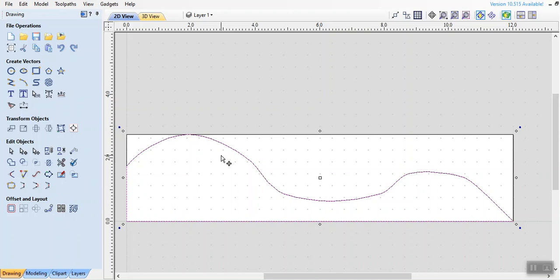Okay, I think it worked, but I want to test it again. Click outside and go back and check the bottom line. Click. Everything I have generated is selected. It shows you it is selected. I can see that. If you don't see it, I can come and help you over there, but it's supposed to be created, generated. Okay, so now I created a closed polyline here and another closed line on the top.